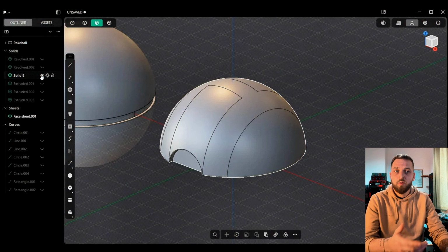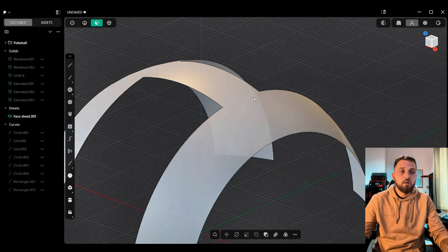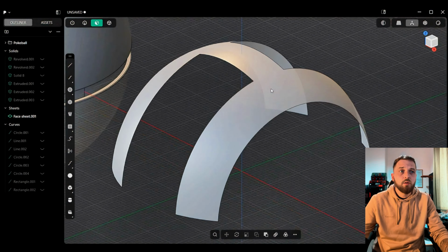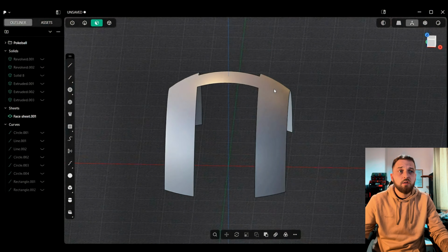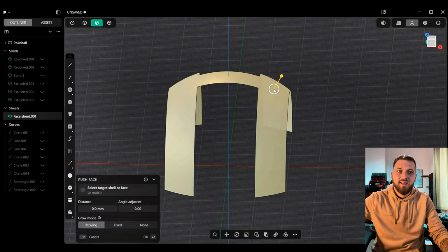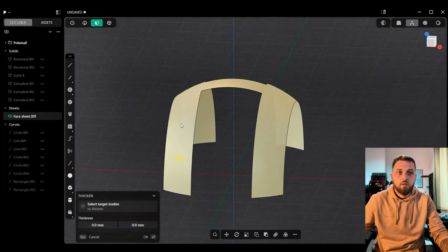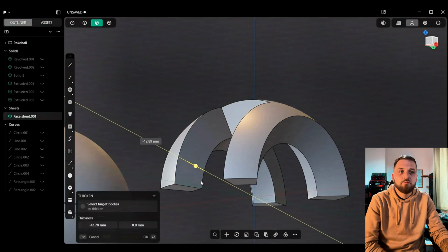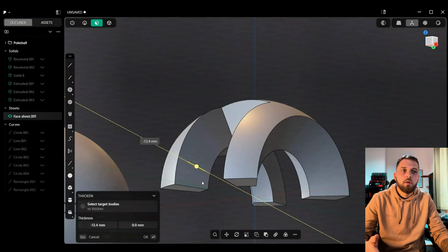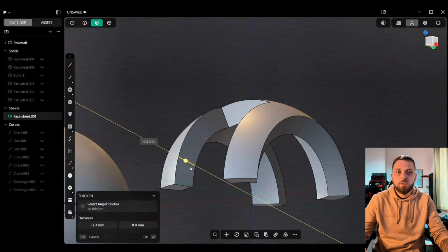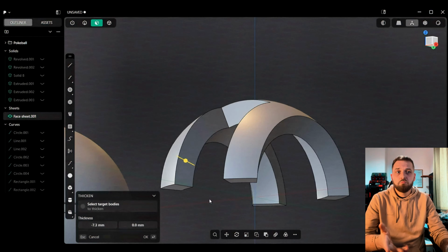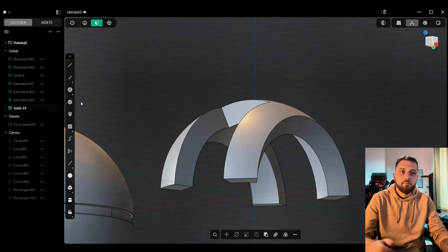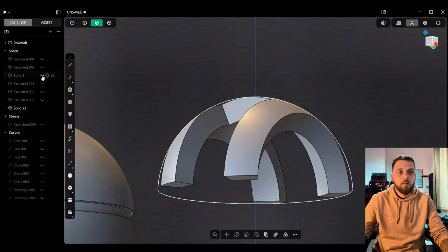So hide that normal body. You'll see this. It has no geometry to it, like no thickness, none of that. So what you can do now is you can click this. You press Alt T. That's for thicken. And then you'll bring that in. We can either bring it in a little bit or just all in like that or further. But you don't have to. So if you bring it in like this, again, right click, that's confirmed it. You can then hide that original sheet and then bring that body back